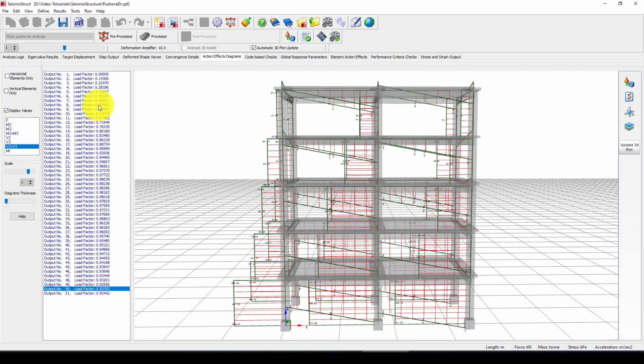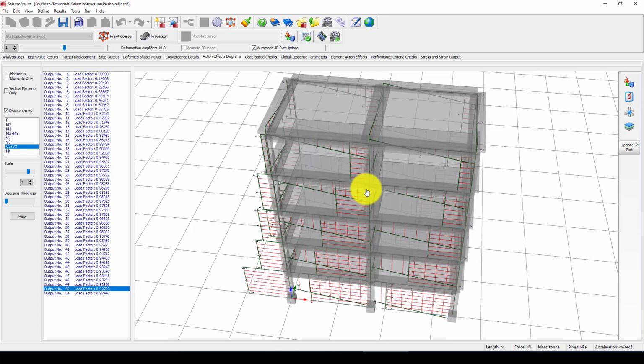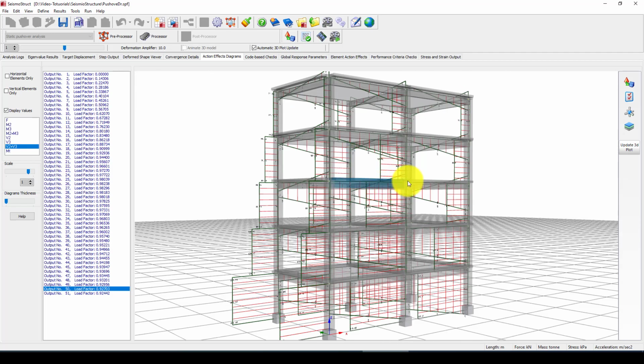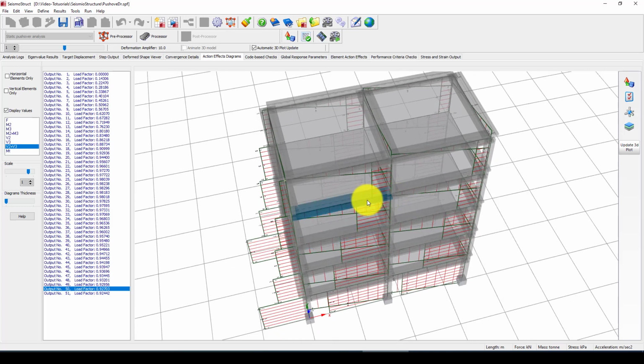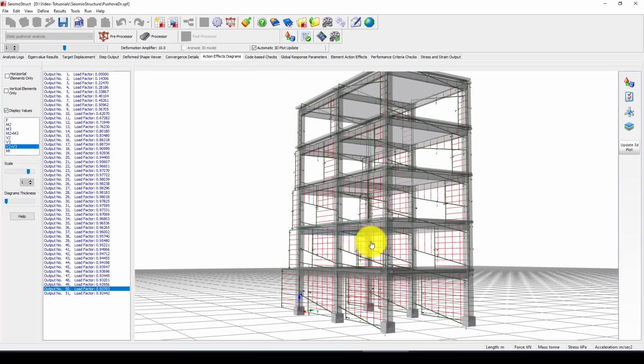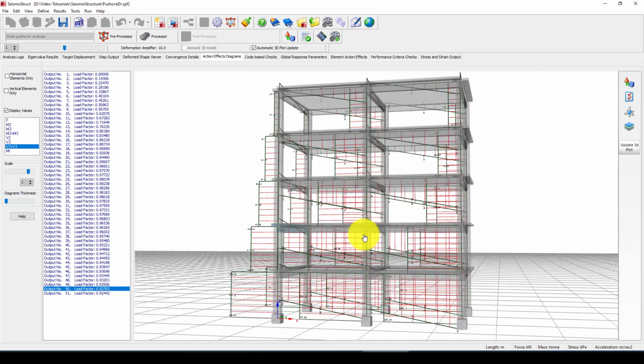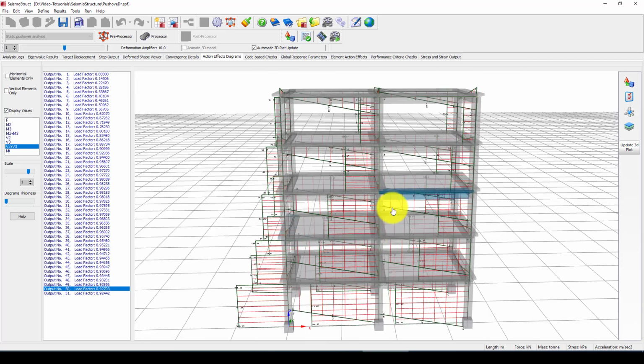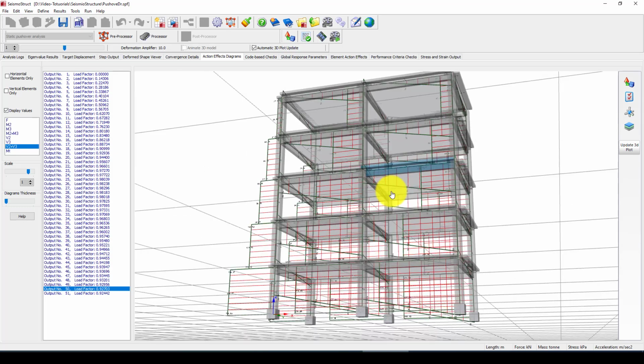After this is finished, you get the result, and then you will go back to retrofit. You will see the present earthquake requirements, get the base shear, and then design this structure again. Like this, you will conduct your study and finish your work.